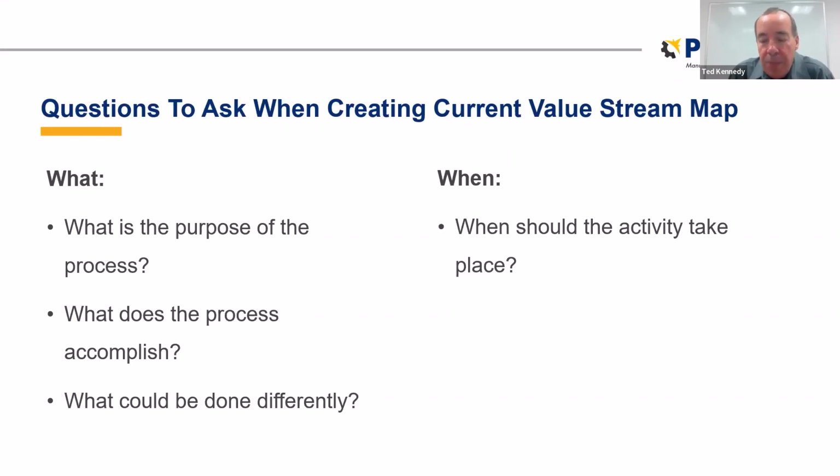If you have a person doing an operation and you assign them to inspect their work after they pass it on to the next person, maybe you don't need a separate inspection operation between the two. And also look at when the activity should take place. Maybe you can have it take place at a different time period, or have it take place while another operation's processing to cut some of the time down in the entire operation, to get the order out.